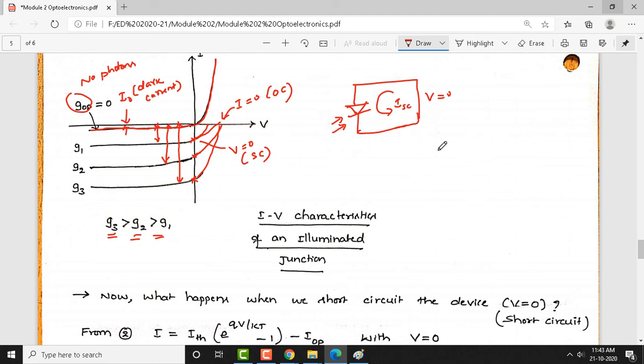Now, when you make an open circuit here with a photodiode, there is an open circuit now. Let us call this VOC, the voltage now applied across these two terminals. Current is going to be 0 here, there is no current, but you can calculate the open circuit voltage VOC. So, two different aspects you need to discuss to understand these curves in the fourth quadrant.